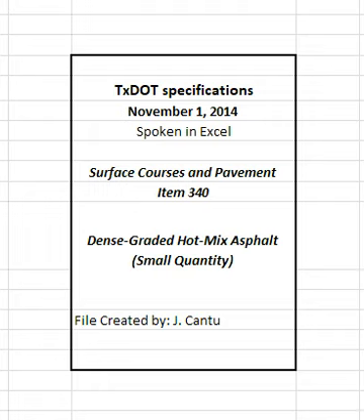2.7.2 RAS. Use of post-manufactured RAS or post-consumer RAS, tear-offs, is permitted unless otherwise shown on the plans. Up to 5% RAS may be used separately or as a replacement for fractionated RAP in accordance with Table 4 and Table 5. RAS is defined as processed asphalt shingle material from manufacturing of asphalt roofing shingles or from re-roofing residential structures.